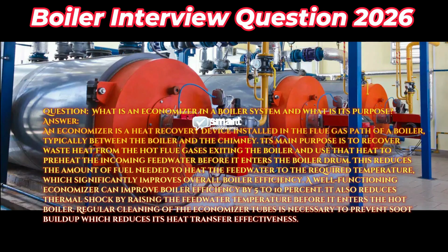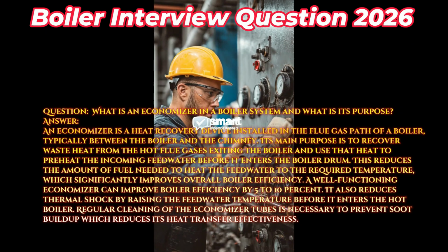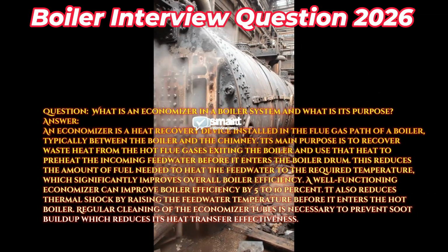Question: what is an economizer in a boiler system and what is its purpose? Answer: an economizer is a heat recovery device installed in the flue gas path of a boiler, typically between the boiler and the chimney. Its main purpose is to recover waste heat from the hot flue gases exiting the boiler and use that heat to preheat the incoming feed water before it enters the boiler drum.